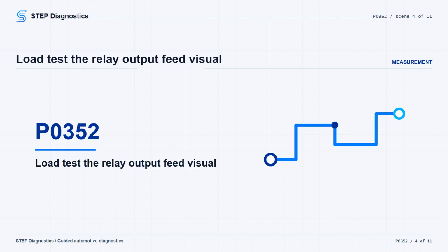A 3156 bulb has approximately 6.0 ohms of resistance and draws approximately 2.0 amps of current. A high impedance test light drawing less than 0.1 amps can miss resistance in the circuit, so the tool being used should draw more than approximately 0.75 amps. The load test bulb should be illuminated and bright.